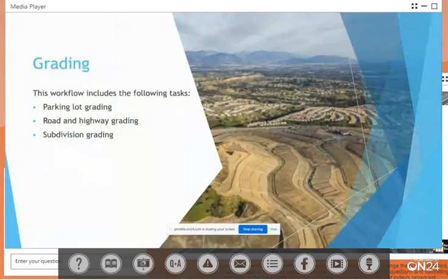And then if we start getting to the grading, and grading is always point to point, rise over run. But with the Civil 3D tools, everything is dynamically updating as we work with our model and based upon our design parameters. In AutoCAD, we're talking rise, over run, and interpolation.